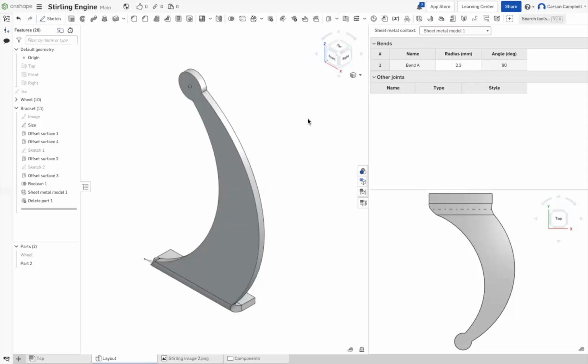The only problem with being in that hybrid world of working with surfaces and solids is you end up with all these surfaces. So to clean my model up, in the folder, typically at the bottom of the folder, you'll see a delete part. I always get rid of them, because at the end of a 200 feature part, you end up with so many surfaces, it becomes unwieldy. You want to get rid of that reference geometry. This is just the standard design pattern. Why is there even a delete part feature in here?